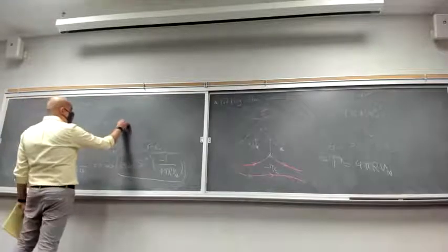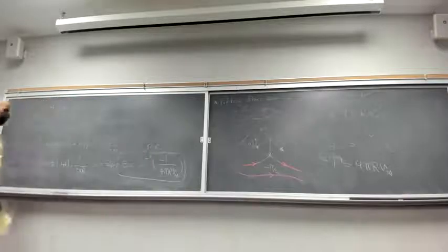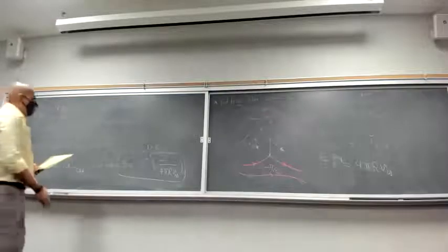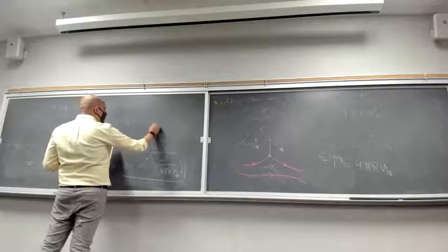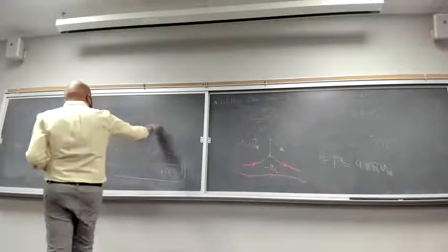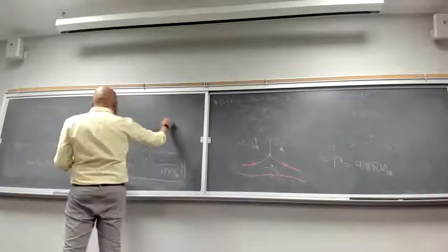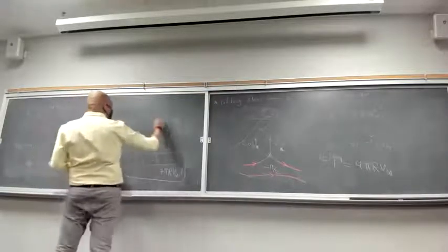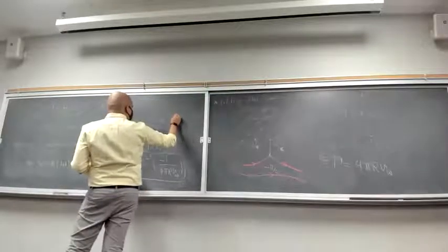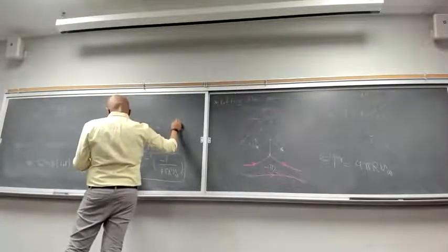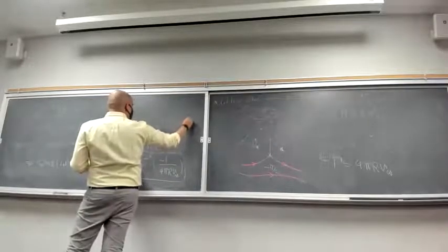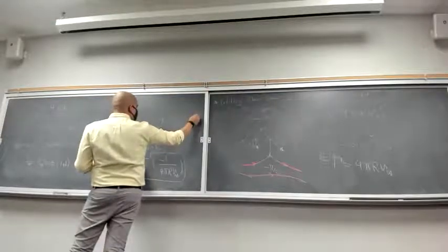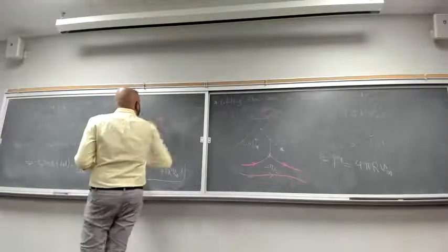And if you plug in the value, you can calculate the r here. I'm just going to go back to my notes and write the value here. r is going to be equal to gamma divided by 4 pi v infinity, plus or minus, it comes from this plus minus, right? Because you're going to get plus or minus 1 here, a square root of gamma squared divided by 4 pi v infinity squared, again, yes, minus R squared. And this is the whole square root.